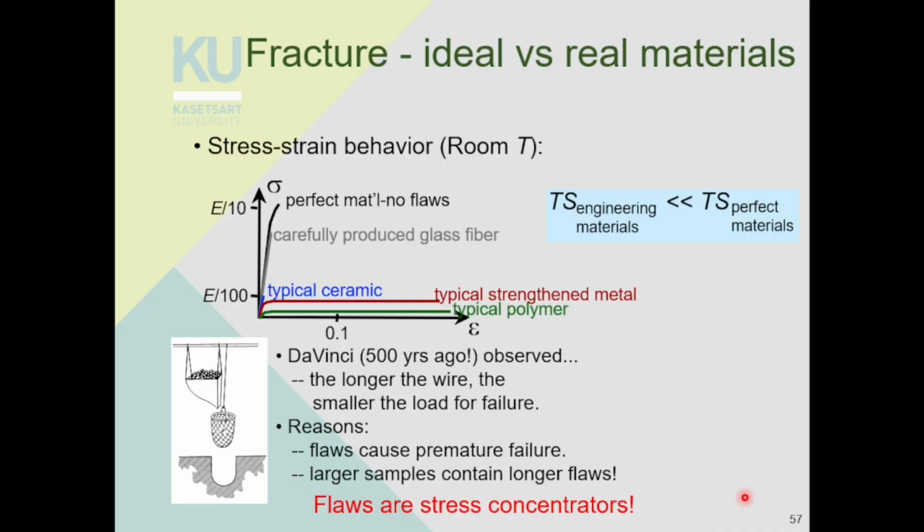There's a simple experiment that you could try. If you have a glass stirring rod and you try to bend it, it might break quite easily. But if you take that same glass stirring rod and dip it in hydrofluoric acid for like 5 to 10 minutes, it will become stronger, not by any magic, but because hydrofluoric acid will etch the surface. It will eat away all the shallow cracks on the surface, making your glass stirring rod cleaner with fewer flaws. So that makes it stronger.